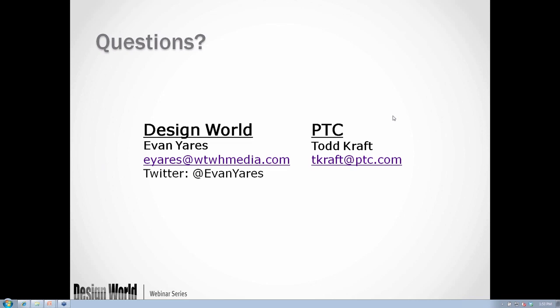Yeah, a lot of these are little detailed questions. Another question from Andre Van Voorst is, any improvements in Pro Mechanica? I'm trying to keep the context of Wildfire 5 to Creo 2, but even since Wildfire 4 we've been making dramatic changes to Mechanica, today called Creo Simulate, by adding nonlinear materials. Now we can do large deformation with contact and load histories. We have a new meshing type called a thin solid.